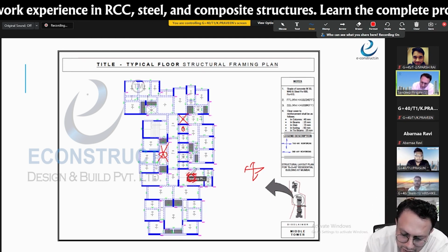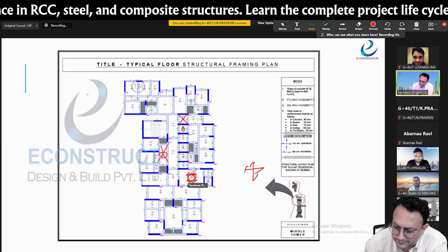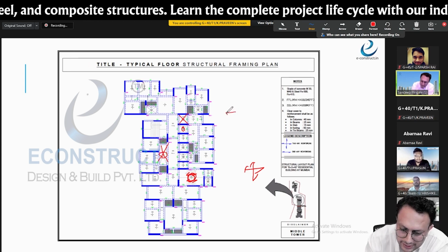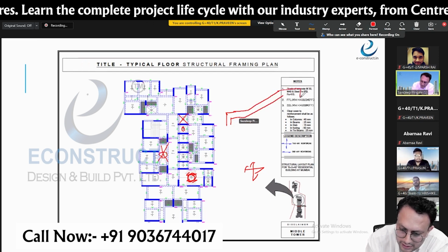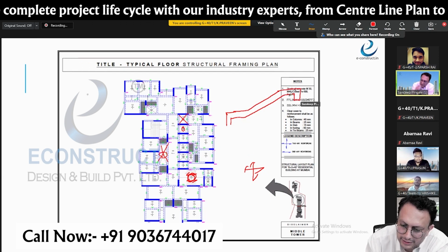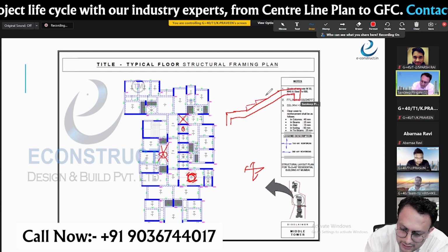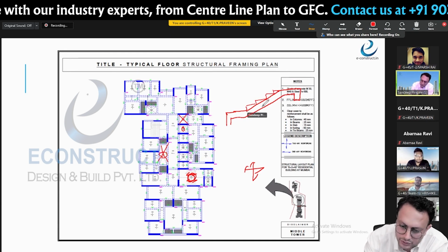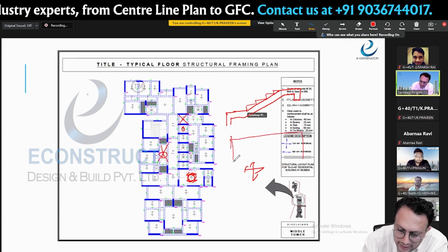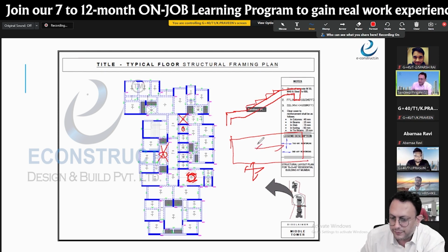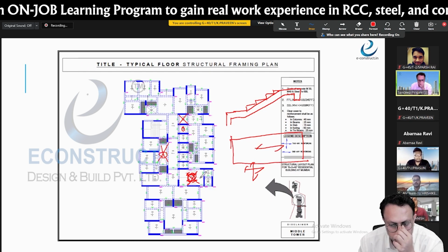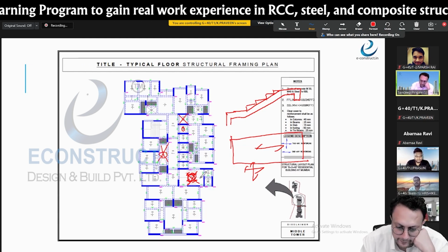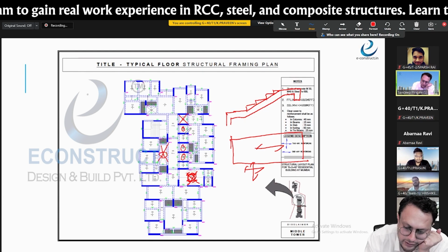स्टेयर केस का स्लैब कभी ऐसे टू वे रहता है क्या? How the staircase goes, it is basically like this, right? It goes like this. It is like this, am I right? And there are steps here. Am I right? So it goes as a one way. If you see that in the plan, it goes one way like this. Correct? It cannot be like this. Correct, no? And wherever the opening is there, please do not mark the slab.